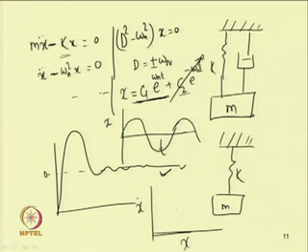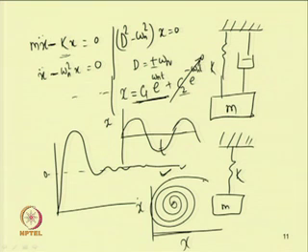So, starting from a very small initial condition, with time one can see that this response will grow. That means if we perturb from the initial condition, then in this case, a system with negative damping and negative stiffness, the system response will grow, and with time it will be very large. So, there will be large amplitude of vibration, or the system may become unstable.